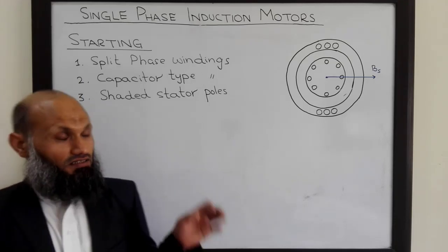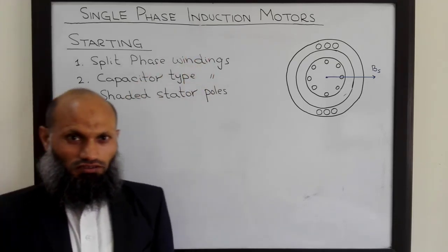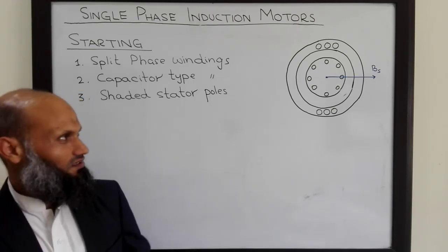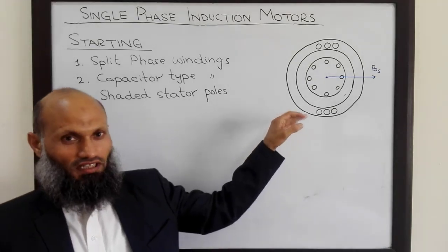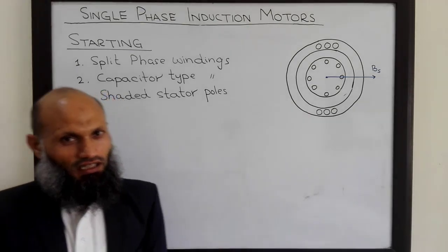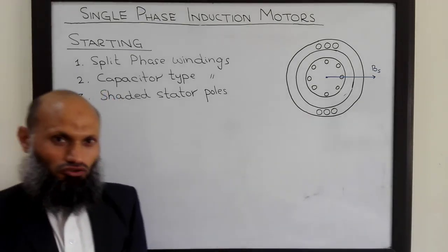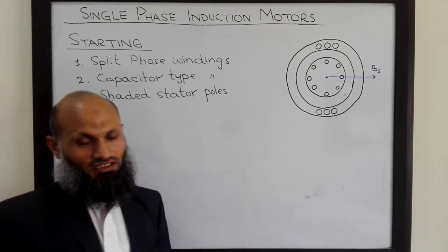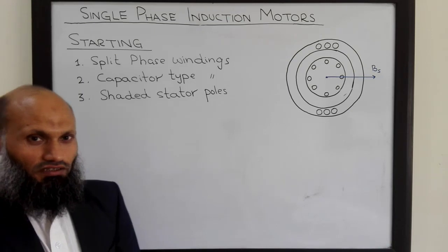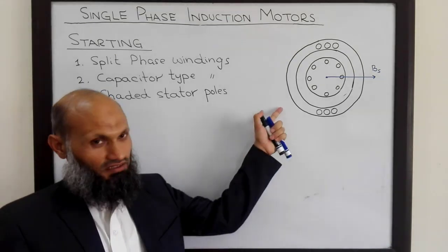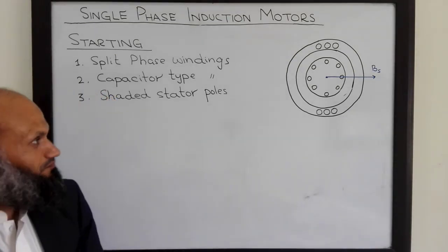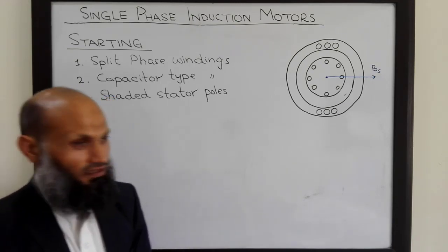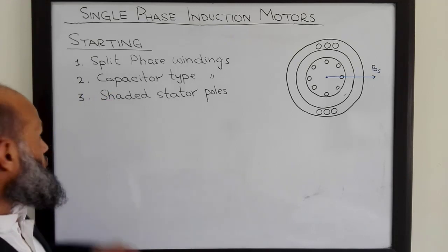Assalamualaikum. Simple single phase induction motors suffer from two problems. Firstly, these single phase induction motors are not self-starting, and secondly, the induced torque in these motors is pulsating in magnitude, and therefore there are vibrations in such kind of single phase induction motor. So how to resolve these two problems? We shall discuss these solutions in today's lecture.